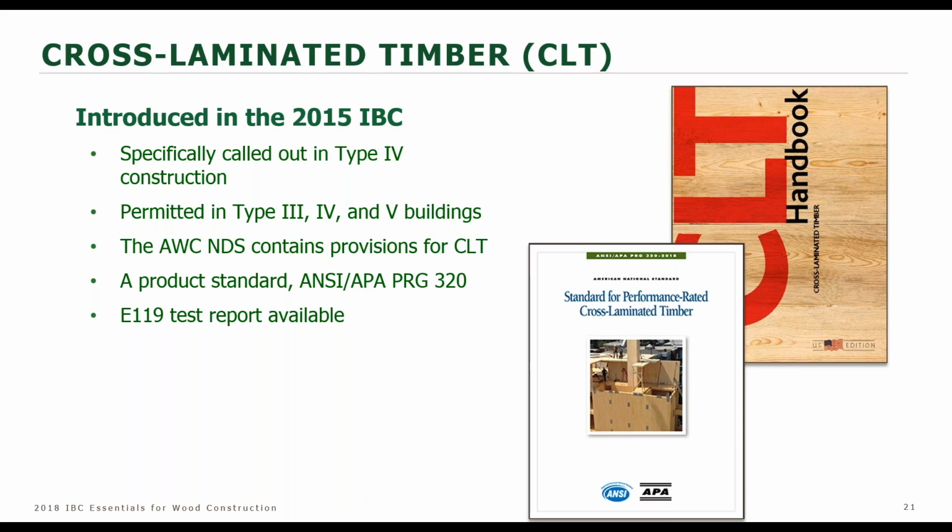It has its own product standard, and there are test reports available. In addition to E119 and standardized test reports for fire resistance, there's not much non-standardized testing for compartment testing of full-scale structures using cross-laminated timber. So it's fascinating, it's new.